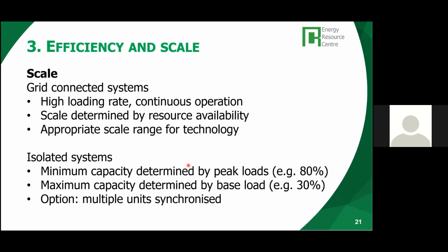And if you have higher loads in daytime and evening, you could run a second, larger generator in parallel, so that the generator capacity better matches the occurring loads under all circumstances.